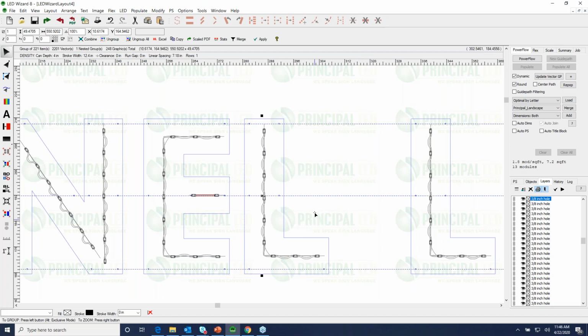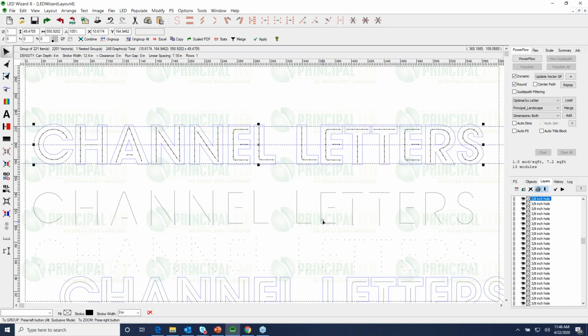In some cases it comes out real clean, right? If you're on a raceway, you can put the wiring holes all within the range or on a guideline that's the center of that raceway, and that's a pretty clean way to do it. So that would be an option as well. Okay, so that's the auto mounting holes tool.